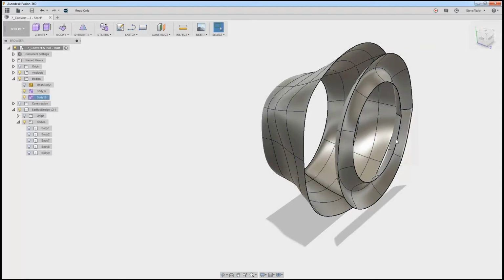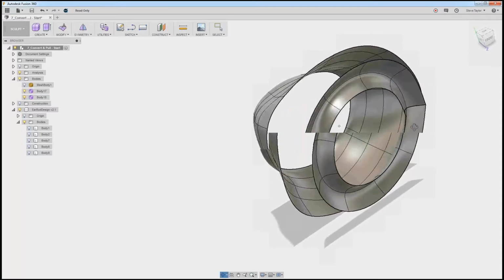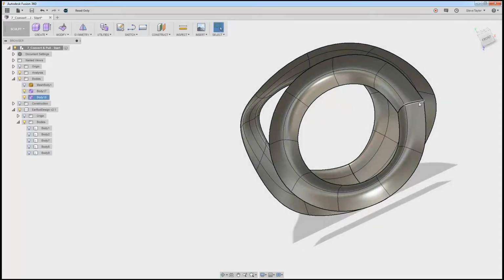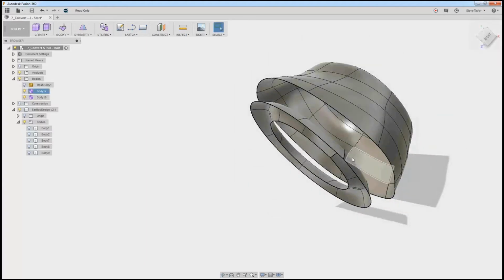Now, one thing to watch out for is creases in our models, which will be viewed as a hard line. If you look on this now, you can see on this bit here, it's like a thick, darker line of these lines. That is because it's actually creased, and if we look at the model there, you'll see there's a bit of a lip where it's creased.